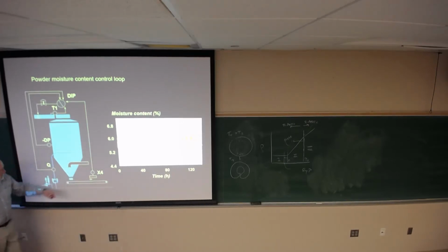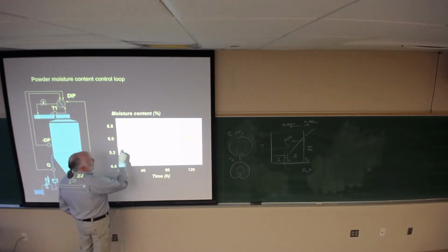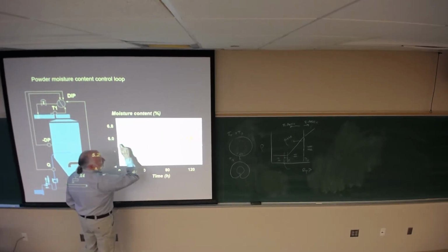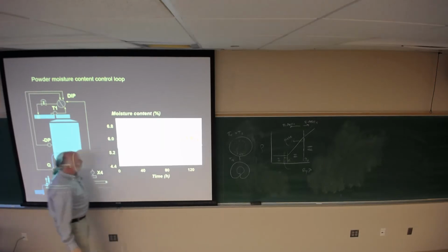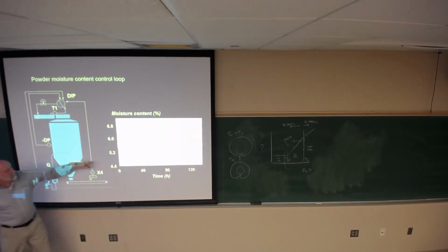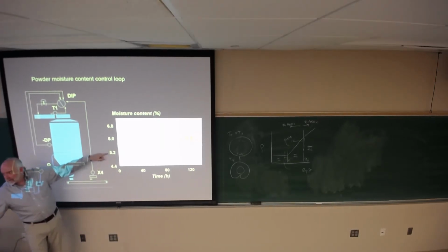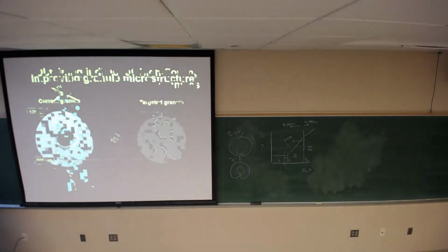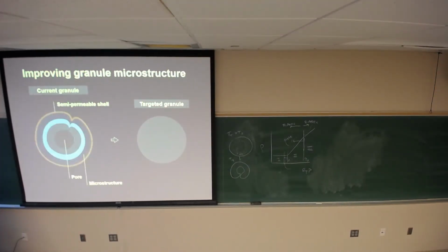By looking at this, they feed back and control their flow rate, and they're monitoring the temperature coming in. And now instead of being out here, they're operating within this gold yellow color in the middle. You see that their moisture content uniformity is much narrower. This is only 0.8% moisture content to begin with. But by doing so, they substantially improve the fill behavior of that material, and therefore the yields in terms of time. So, cartoon version of what's going on.